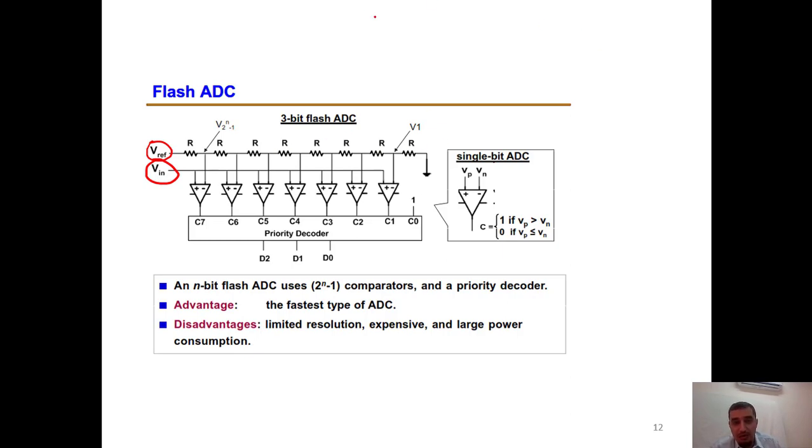What is R equivalent for these resistors? So this resistor is connected from this side to ground, and this resistor is connected from this side to virtual ground. Okay, so these two are in parallel. R in parallel with 2R. R in parallel with R is half R, plus R is 2R, and so on. We get the equivalent resistance at the end equal to R.